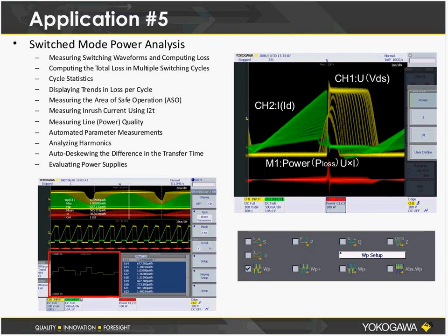Another area that's receiving a lot of work and attention these days is energy efficiency and power measurement. Traditionally, oscilloscopes have been used to measure just voltages and physical transducers, but at the same time, we see a lot of users using current measuring transducers or current probes to measure the current consumption of their device, and in combination with the voltage, you can actually measure the power consumption in watts or watt hours and so forth.